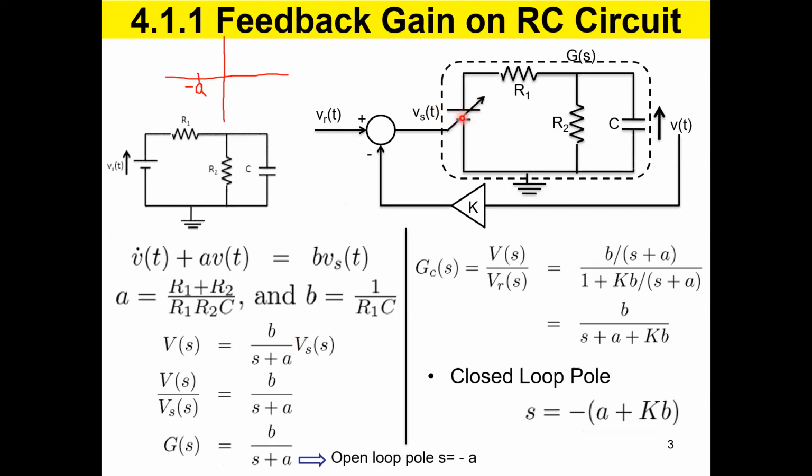This one. This is the control voltage, right? So if you want to monitor the control voltage, you have to make the control voltage the response. So for that, you need to have an additional transfer function, not the one we have already, which is V over VR. Now you need to generate Vs over VR. So how to do that?